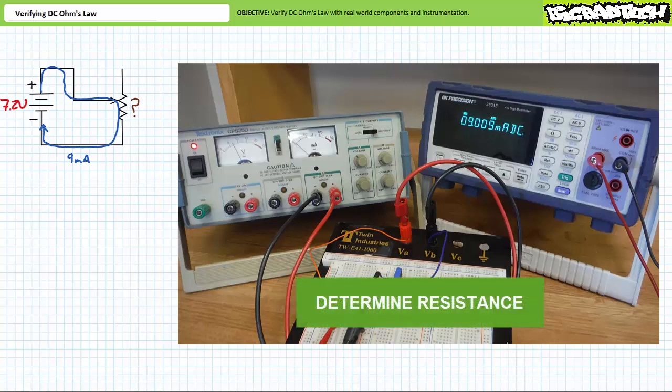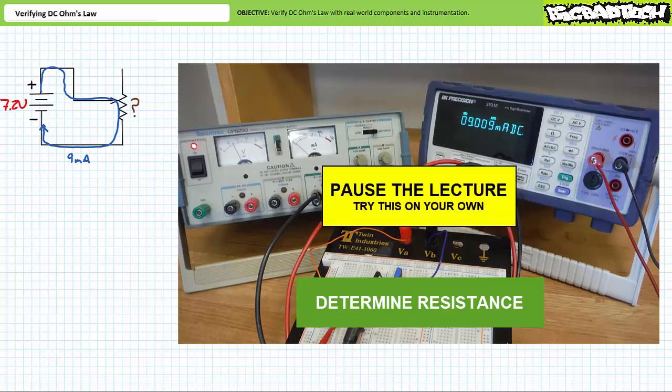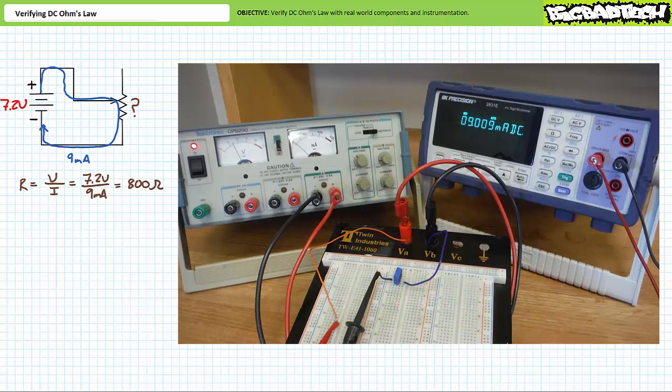As an exercise to the viewer, I invite you to calculate the resistance necessary to allow 9 milliamperes of current to travel through a potentiometer experiencing a 7.2 volt drop. By all means, pause the lecture and try this on your own. If you're tracking, you should have obtained the following results. An application of Ohm's law demonstrates resistance as voltage over current. Substituting our observed values yields an anticipated resistance of 800 ohms.